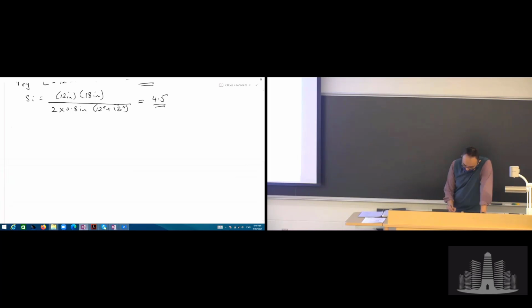Before we move on, any questions, guys, about this? Step number 5 is compressive deflection. Now we know the stress, so we want to look at the deflection. The sigma S is, you add all the reactions from the dead, 155, and from the live, 50, divided by LW, so that's 12 by 18, and the answer is 0.95 ksi,